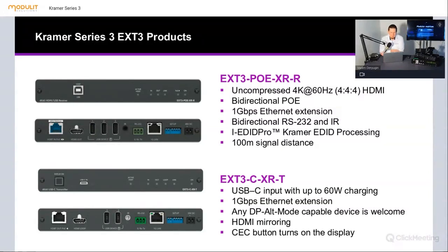EDID Pro by Kramer. It's a great thing just to work with the EDID data, because sometimes you need to adjust the receiver side in order to give the display or the projector the desired resolution or signal format to be correctly processed and displayed, and to obtain the maximum possible quality of your visual perception. Okay.